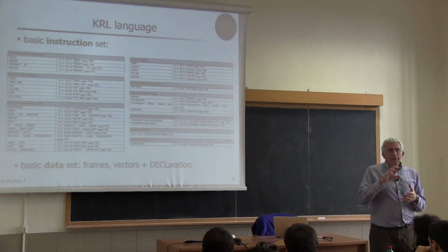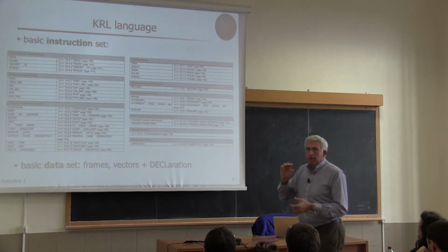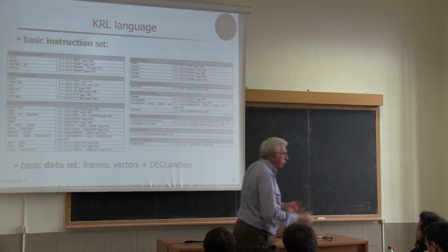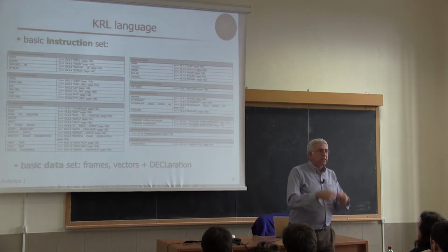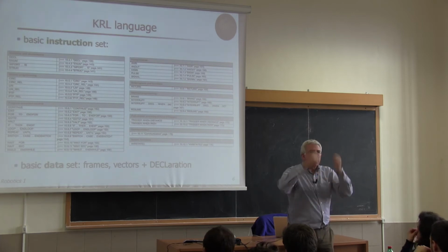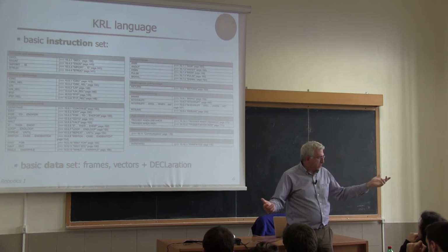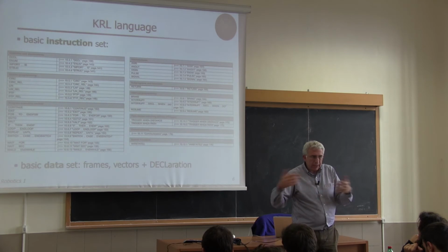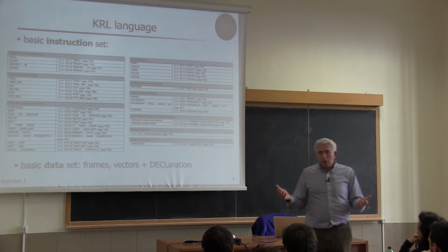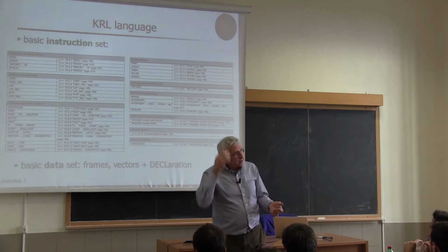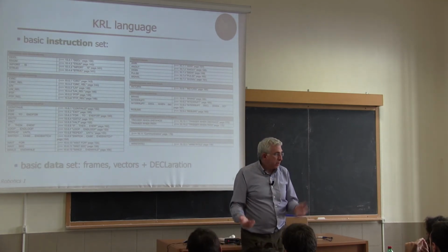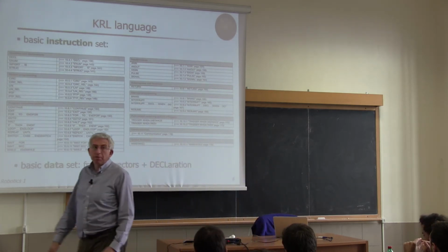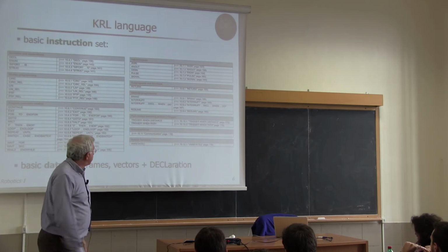Unless we define some low-level interface where we define directly the results of this planning at the joint level, and then the controller takes just new positions which are just sampled out of a very complex path. It's like solving inverse kinematics point after point. Okay, we will see how this can be done and what the options are when we talk about trajectory planning in the Cartesian space or in the joint space. There we will see all the options, or a few options, the most important options for programming motion.